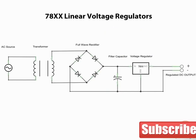This is a typical application for 7800 positive voltage regulator. We start with an AC source. The step-down transformer drops the AC voltage to an acceptable level for the input of the 7800 regulator. Next, the AC signal passes through a full-wave rectifier bridge and then is immediately filtered by the filter capacitor. This then presents a DC input, yet unregulated signal to the input of the 7800 voltage regulator. The 7800 takes this signal and provides a regulated signal at the output.